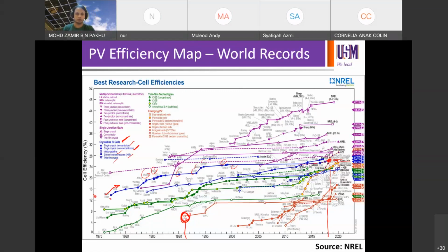So you can also look into other technologies. If you stack the solar cell with multiple junctions, PN on PN on PN on PN on PN, you will end up with multi-junction technology. That will give you even higher efficiency, but at higher cost. For example, this NREL 6 junction, 6J here means 6 junction. PN on PN on PN on PN on PN on PN, 6 stacks. PN one cell, PN second cell, PN third cell, fourth, fifth, sixth cell. So altogether, that will give you about 47.1%.